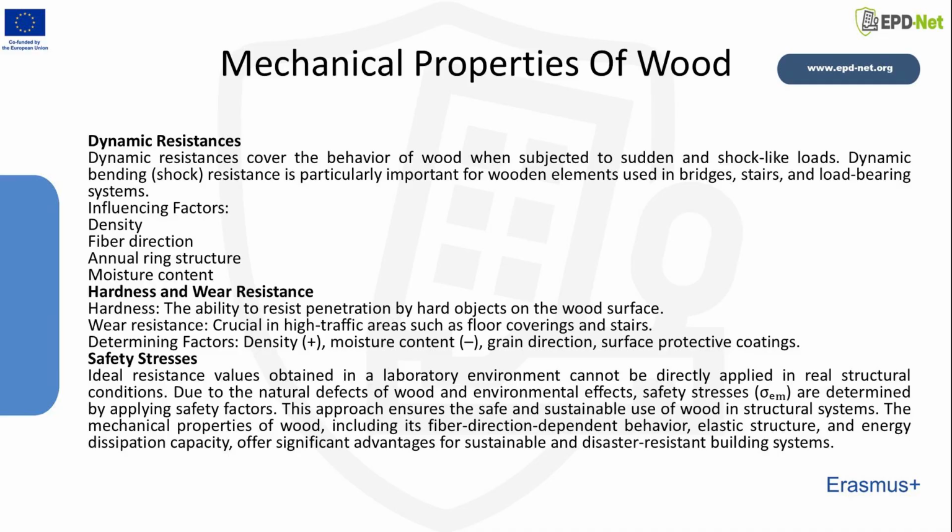Hardness and wear resistance are also important mechanical properties. Hardness refers to the ability of the wood surface to resist penetration by hard objects. Wear resistance is crucial in high-traffic areas such as floor coverings and stairs. These properties are affected by density, moisture content, grain direction, and surface protective coatings.